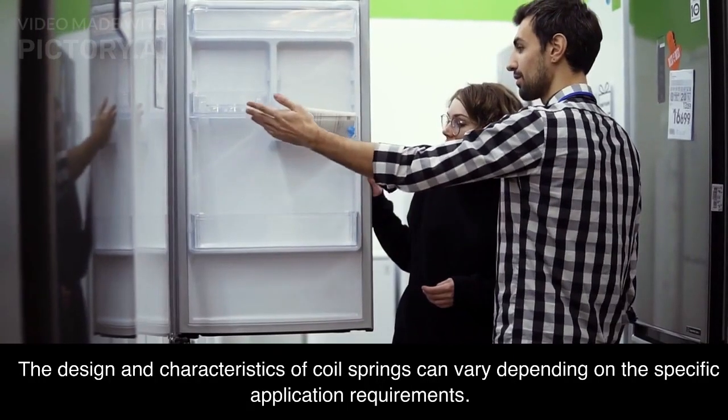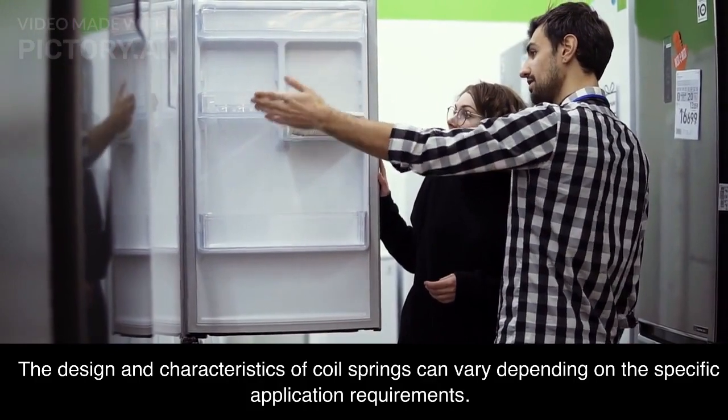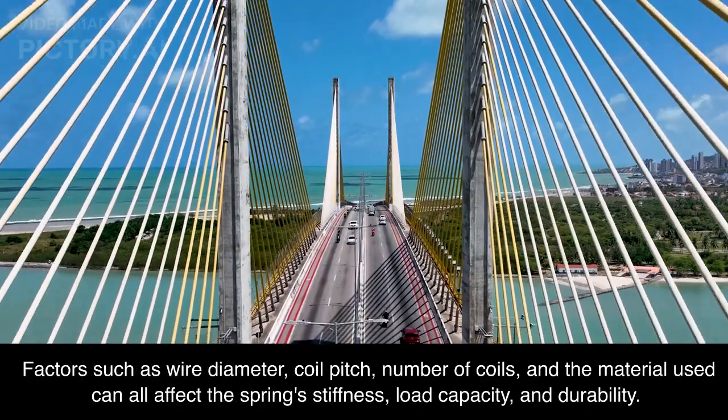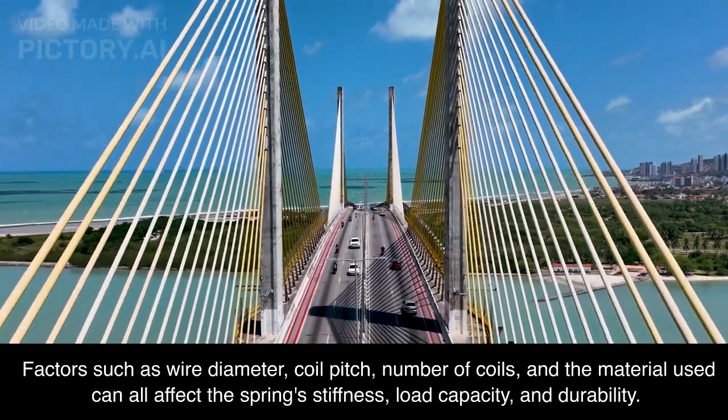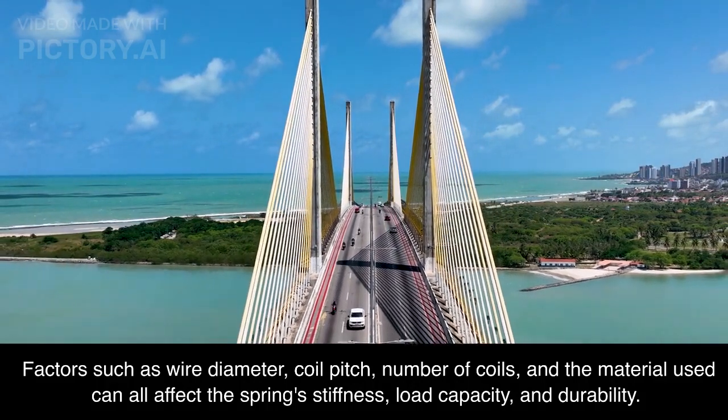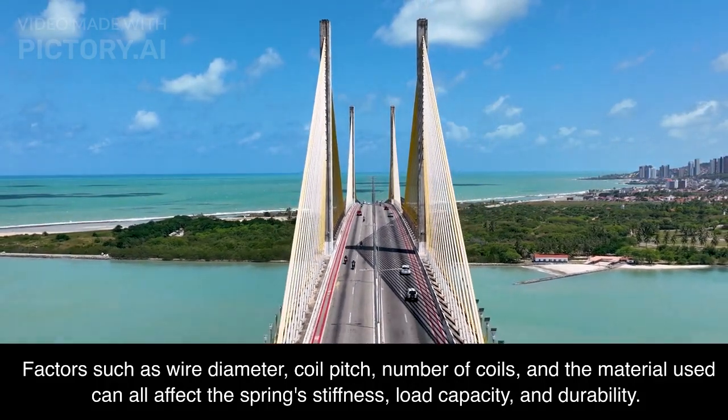The design and characteristics of coil springs can vary depending on the specific application requirements. Factors such as wire diameter, coil pitch, number of coils, and the material used can all affect the spring's stiffness, load capacity, and durability.